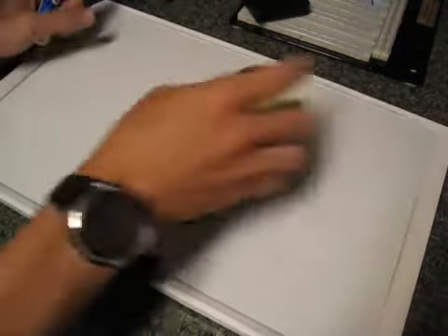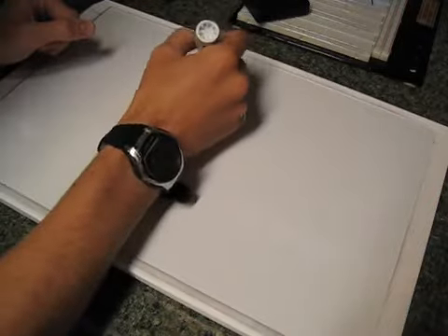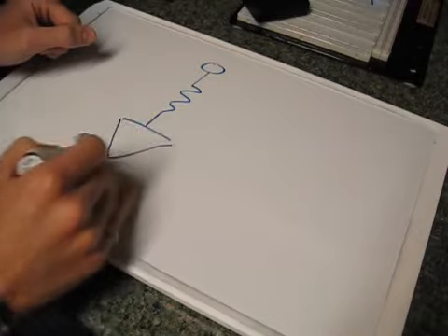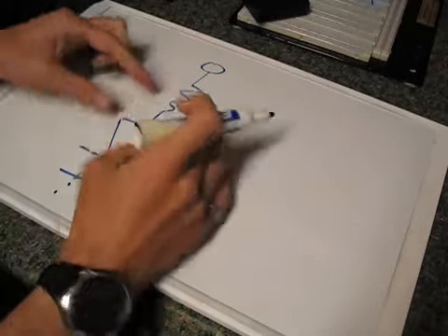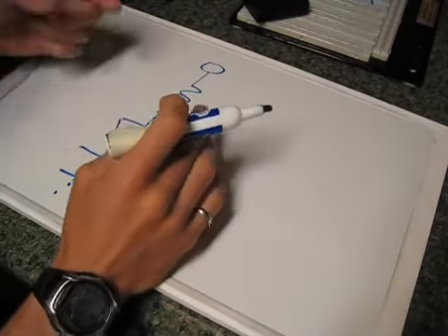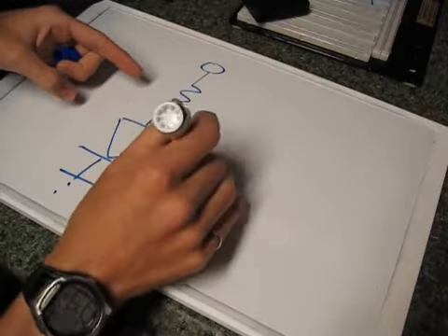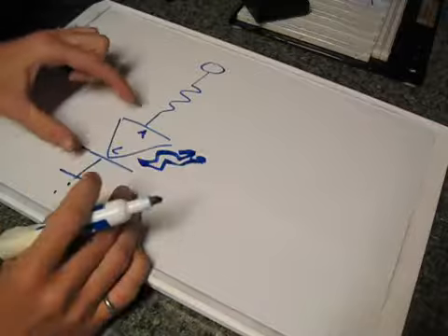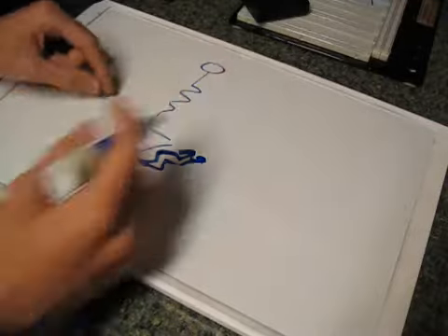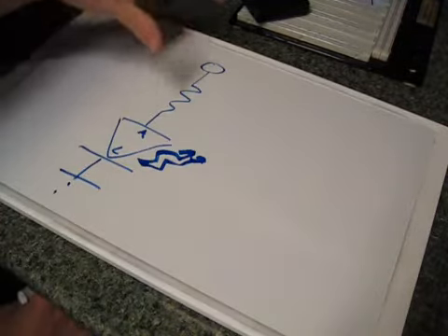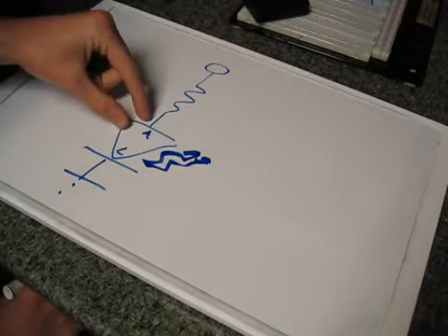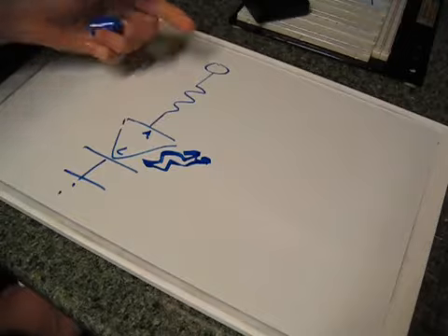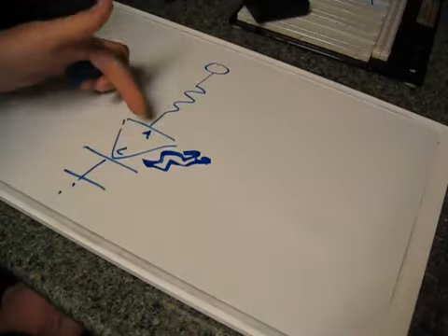Okay, so let's start off with our circuit. You have your power source here, you have your current limiting resistor, and you have your LED. Now remember, LEDs are polarized, and they kind of behave like diodes. So you need to have your anode and your cathode lined up. If your current's flowing down this way, if you have your power source up here, that needs to go to your anode. You can think of it like the positive sign on a battery.